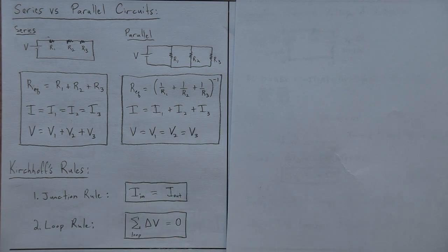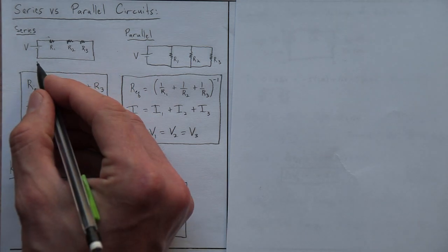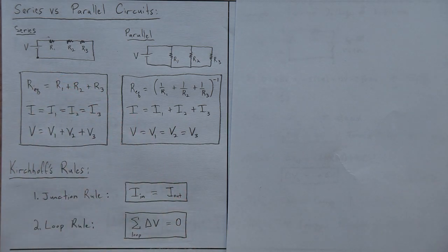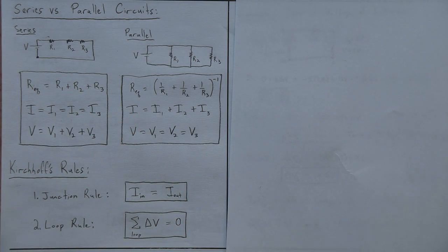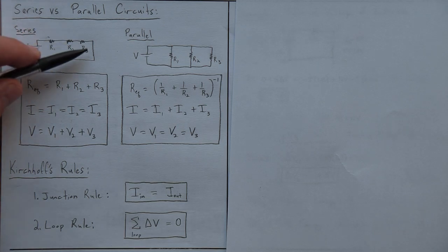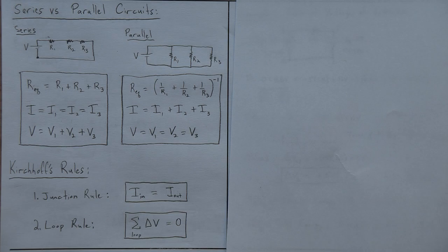The loop rule says that in any given circuit, the sum of the voltages has to be 0 when you tally the voltages going around a circuit. That's basically this expression right here. If I mark this as a starting point, remember I said with Kirchhoff's rule at the time, imagine you're a little ant with a little tiny voltmeter walking around this circuit, measuring all the voltages and adding them up. The sum in the end is 0.